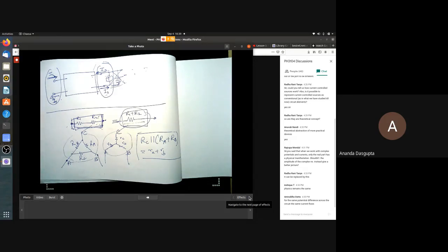equivalent circuit thing means. So as far as, say, a two-port network is concerned, for example, if you replace the two-port network by its two-port equivalent, voltages and currents in the outside world will not change. Inside, of course, something very messy has happened. Earlier inside you had maybe a transistor which was taking in a current from one side and pushing a fraction of that in the other, and so on. All that has gone away. You just have an input loop and an output loop. Of course, it's a much simpler situation as far as the equivalent circuit is concerned.